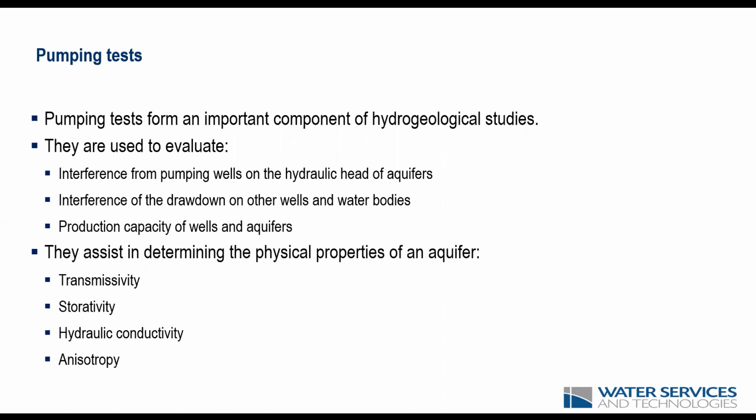Pump tests are an important component of hydrogeological studies, any hydrogeological assessments. We use these sort of tests to assess things like interference from pumping wells on hydraulic head of aquifers, surface water bodies, interference from pumping between abstraction wells, and also production capacity of wells, as well as aquifers.